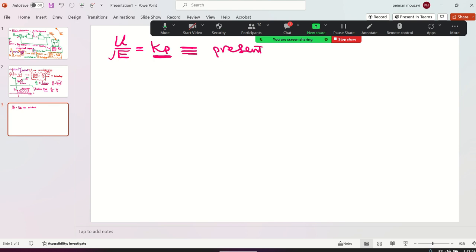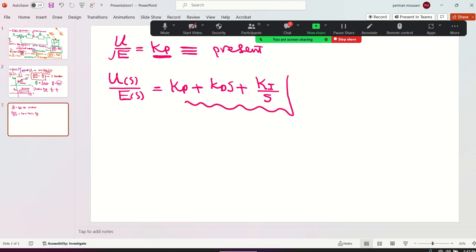So bear with me, I'm not done yet. But a good question. In the coding, I'm going to teach you in MATLAB. So now if I say U of S over E of S is PID, it means KP plus KD S plus KI over S. This is completely PID control. Why didn't I answer your question? Because first I have to teach you what the function of each of these is. Understand?